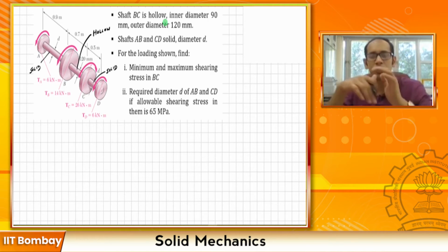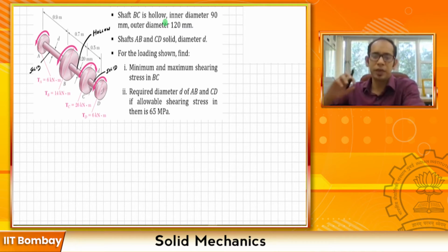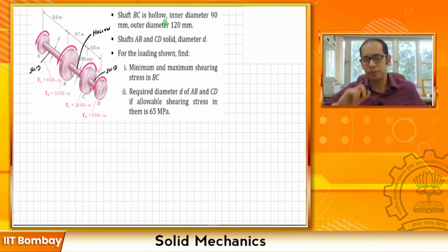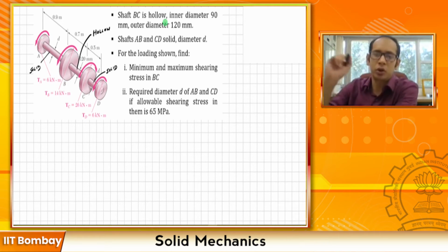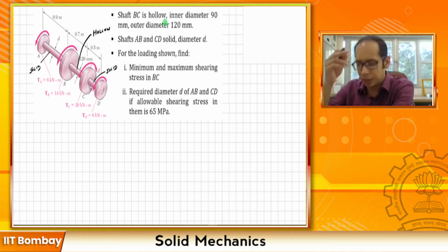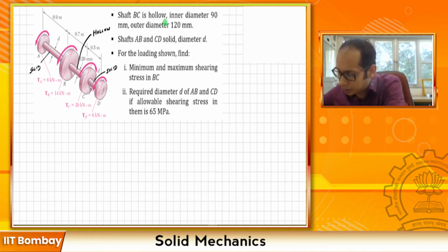Now before we start crunching numbers for this problem, the first thing, as you know, we always have to do is check whether our system is in equilibrium. So let's take a look at whether this entire shaft with all these torques applied is in equilibrium or not. To test that, let's draw the overall free body diagram. I am drawing this in 2D, and we will mark the torques with double arrows, just to make it a little easier for us.